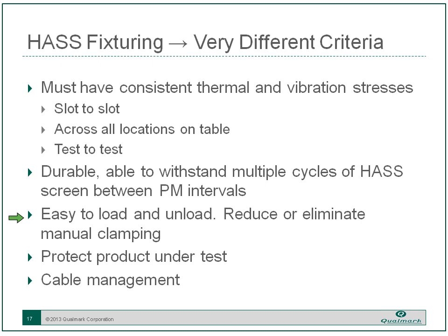And if there's any way to avoid it, you don't want to use nuts and bolts in the load and unload process. That'll typically require torquing every time you put a product in, and you're better off without that if you can avoid it. You also need to worry about protecting the product under test. You hate to damage it while it's in there. And cable management becomes an issue when you have that many products going in. So let's carry through and talk a little bit about some of these characteristics.